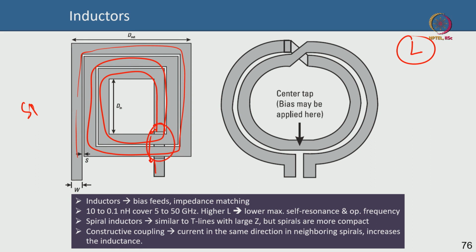The way to fabricate it, of course, is that you have to put down the metal here, cover it with a dielectric, and then etch the dielectric away from other parts, or maybe you leave it at that point, and then you keep fabricating the spirals, and finally you have to make a metal short from the outside to the metal that comes out from below. Okay, and that makes it an underpass. You do not have a metallic short here.